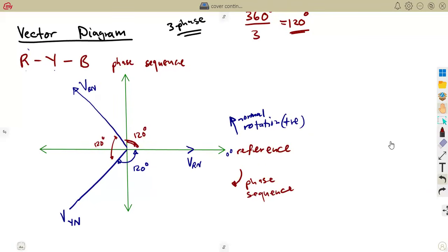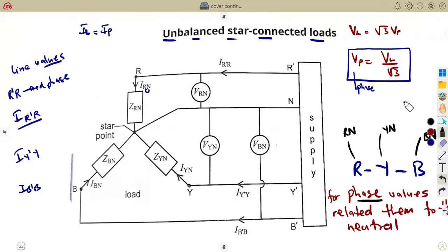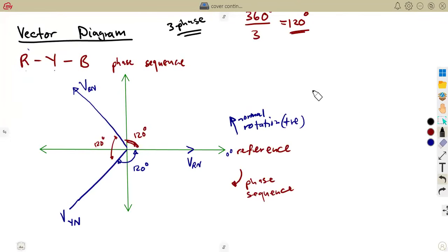Remember, we had here the relationship, like I was saying, that the line voltage is equal to this. Therefore, the phase voltage will be line voltage over square root of 3. You now have the phase voltage. You can use this to find voltages in star. All right. So for voltages in star, let us just make our calculations. We're going to need voltages in star. Remember, this is a star connection or just a star load. Okay. So this is what you're going to need for the voltages.